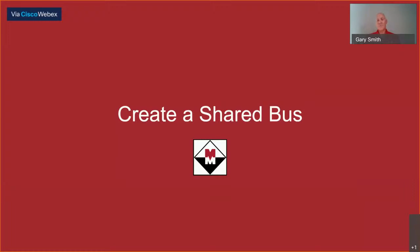So almost finished. So we have completely sized two axes of motion. We have the horizontal axis with a servo motor and amplifier. We have a vertical axis with a servo motor and amplifier. The Kinetics 5700 drive works with a shared bus system. So there is a separate component called a DC bus power supply. And we are now going to create a shared bus, add the axes that we've created, the amplifiers, to this shared bus, and it will allow us to size that power supply and any required accessories.